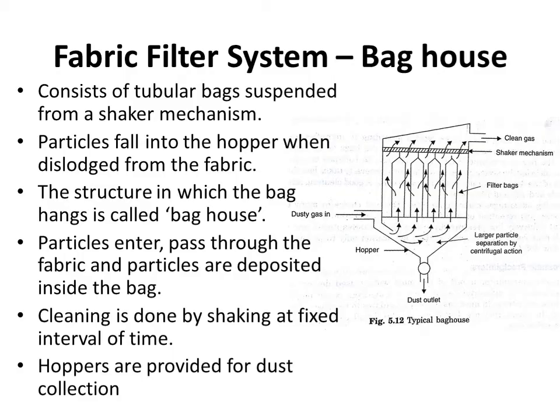The particles enter, pass through the fabric, and the particles are deposited inside the bag. Cleaning is done by shaking at fixed intervals of time. Hoppers are provided for dust collection.